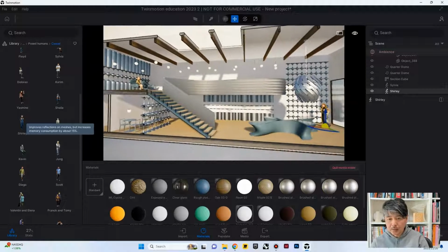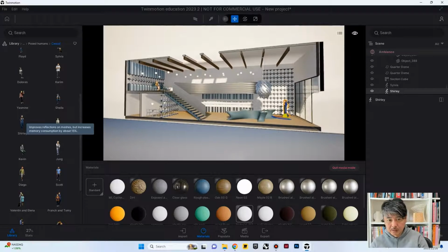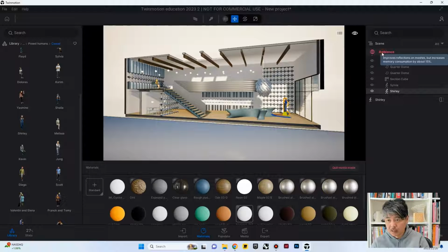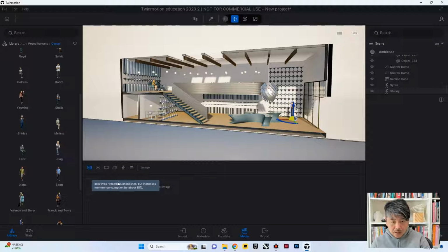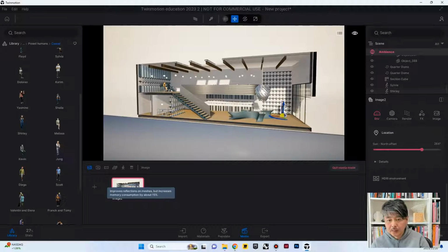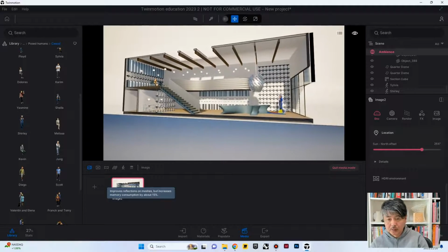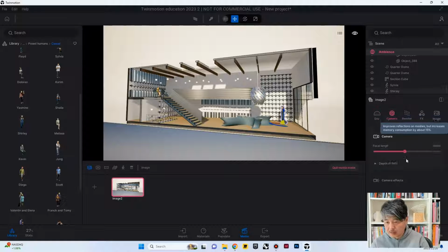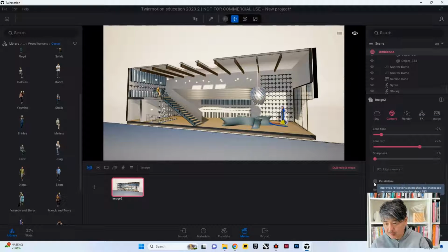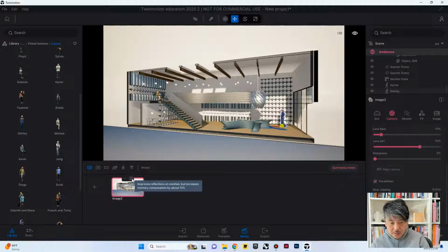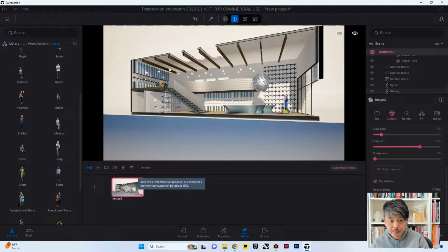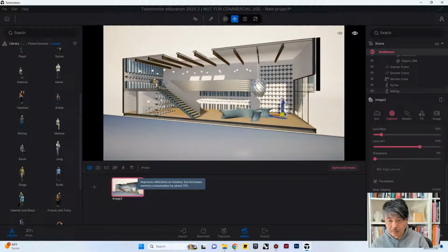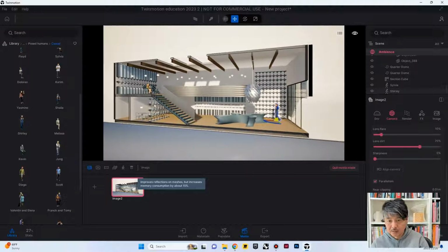Okay, and then think about the vertical line as a very straight line in this case. So you can go to ambience and then let's create a new image under media and then adjust the view. And then you can go into camera setting and then camera effects and then parallelism on. And then you can update the view by clicking this rotation mark and find a view that works very nice and clean for you.